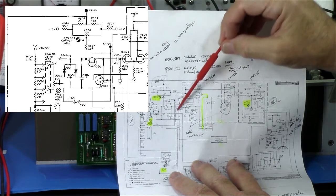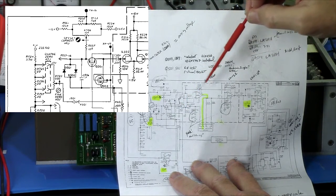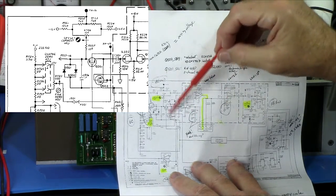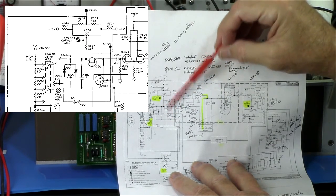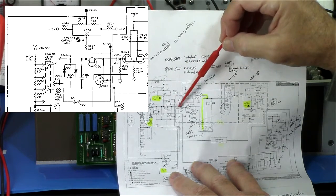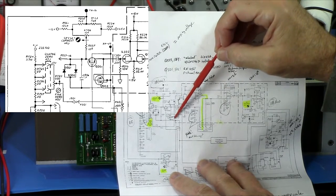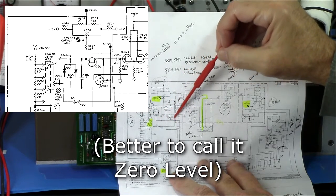So they have discrete FETs here on the input, and then multiple stages of gain, and then there's feedback, and then this is the chopper switch here, which switches between the input signal and ground. Okay. Where's ground? This is actually the ground level here. Okay, so that's coming in there.